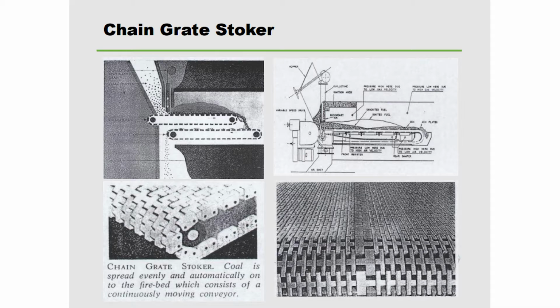For the chambered boiler, the arch is the only heat source available to ignite the fuel, coal or wood. If you have more surface heat available, you can burn a lower ranking coal or wood waste in a chambered boiler. That's its condition. It's very, very restricted.